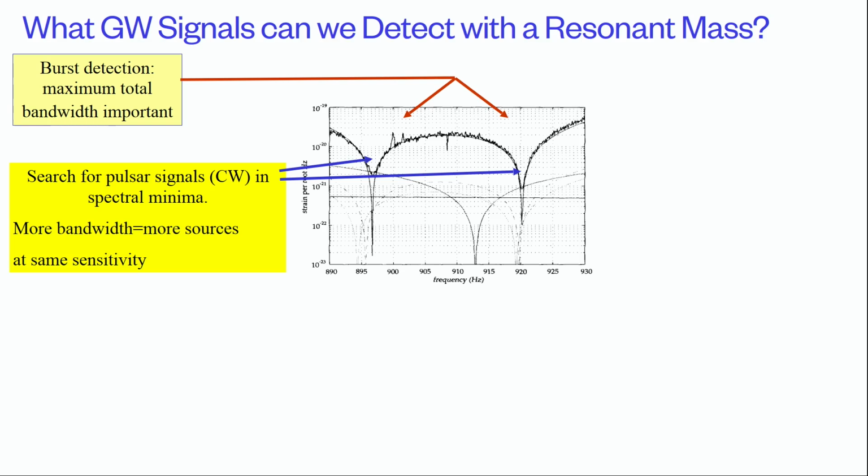I think the integration time, if you were to measure the noise in your detector, that's a very complicated question. To measure a plot like this, instantaneous is badly defined. The spectrum analyzer is going, so your lowest frequency number on that plot is 890 hertz, right? So you can ask the question, what is the distance between 2 points on that plot? Maybe they are separated by, let's make up a number, 5 hertz. Then your spectrum analyzer needs to measure for 1/5 hertz for the FFT to have a resolution of 5 hertz, right? So it's not instantaneous. The spectrum analyzer had to measure for 200 milliseconds.